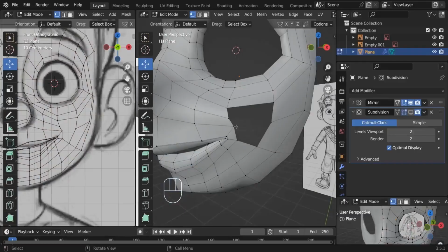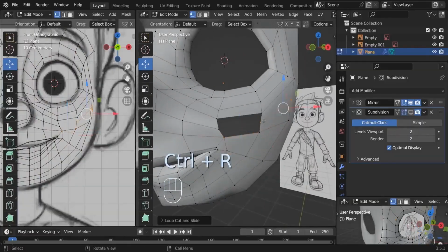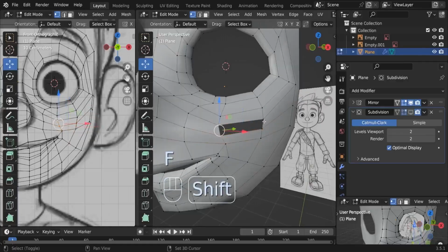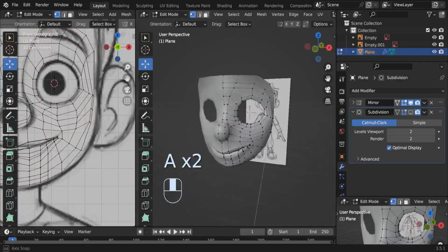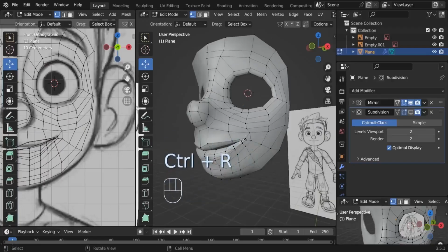So now we're left with this area. So how can we handle it? So these 4 vertices gonna go together. Pretty much good. And we can insert an extra edge loop right here. Let's select these 4, press F, and these 4, press F. Perfect. There we go. So the important thing, let me just show you. So we're having one loop for the mouth, this loop right here.